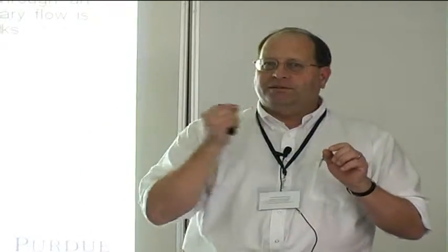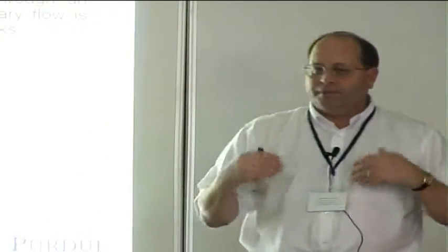Well, we wanted to know how could this be extended such that this control effect could be modulated. Could we get big control, small control? Could we turn it on and off? So that's where the work with David Seng came in, where we tried to demonstrate a fluidic method to create the effects of the step seen by Ong. Okay, so again, going on the theory that, and there's some CFD involved which backs me up on this, but the upstream facing step creates just a little region of elevated pressure. You don't have to get much above vapor pressure to collapse the cavitation.